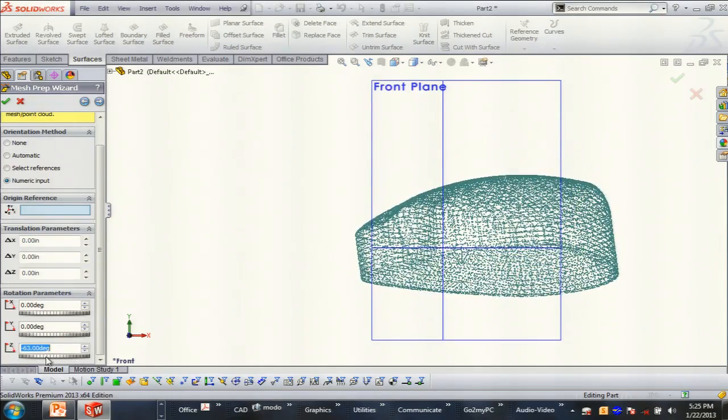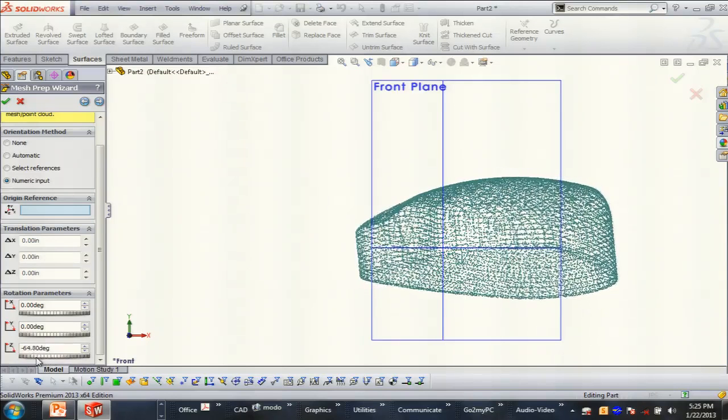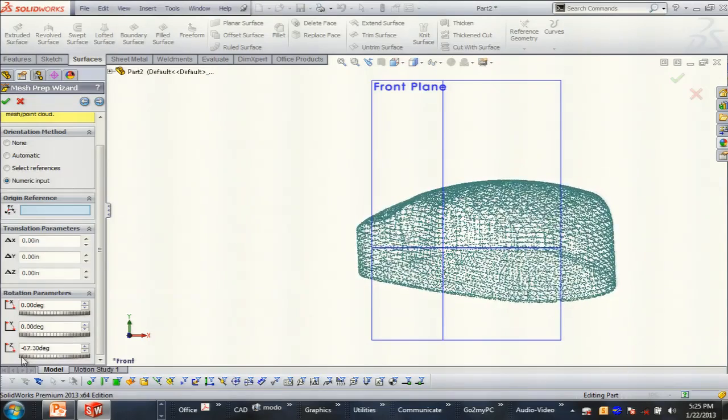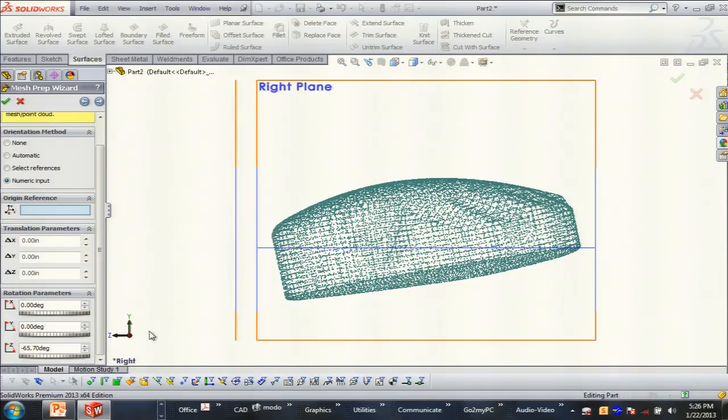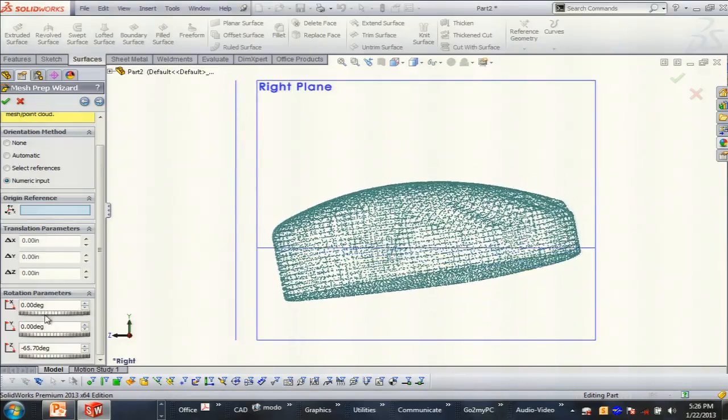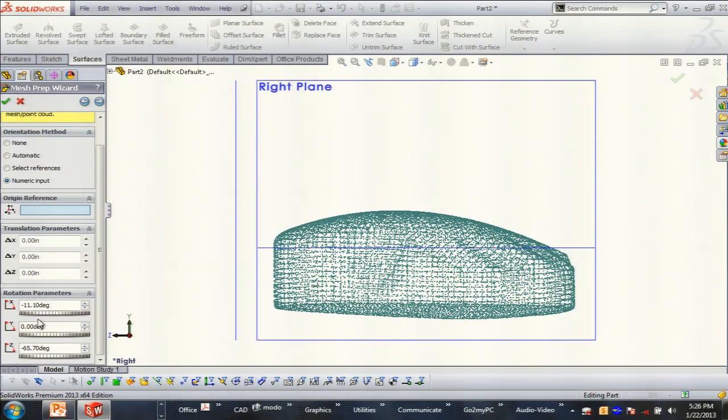And also notice that if you're on scroll wheels in SolidWorks in general, if you hold down the Alt key, it quarters the value of the increment of acceleration. So I'm now holding down my Alt key, and look at my scroll wheels moving much slower. Okay? Let's go to my right view. And now I'm going to work off of my x-axis to rotate.